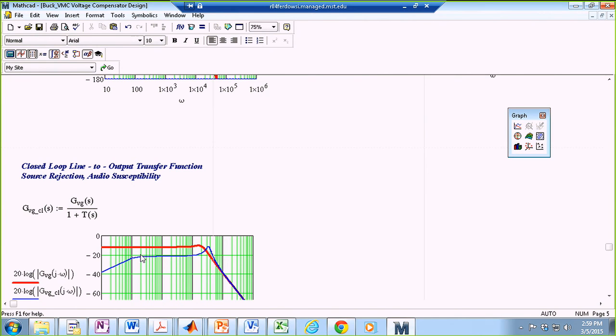So what I'm going to do now is introduce an approach in terms of what our transfer function should look like. We've got to use these Bode plots to fine-tune our final design. And if it works here, it doesn't mean that it's going to work for the rest of your lives. This is just a sample. If you are designing a boost converter, because of the right half plane 0, it might be a little bit more complicated.